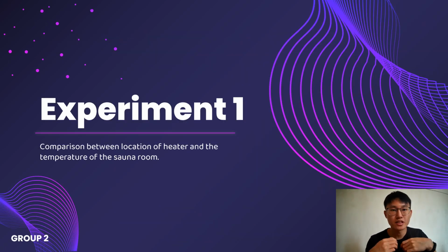Hi, my name is Taeyuzong. I will be presenting the first experiment, which is to compare the location of the heater and the temperature of the sauna room. As we know, the system of the sauna heater is sensitive to temperature. If the temperature is too high, the system will shut down for protection. Therefore, in this experiment, we need to find out the optimal position of the heater to ensure the temperature of the sauna room is high enough but not causing the shutdown of the system itself.